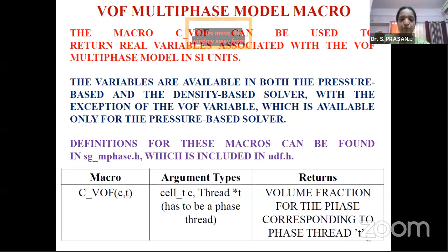As I told you earlier, every software gives you visualization and some result, but whether that result is correct for you, or whether it matches the results of your traditional methods, is not possible to tell just by visualization. So there are macros, not only for volume fraction, but also for velocity and for pressure.